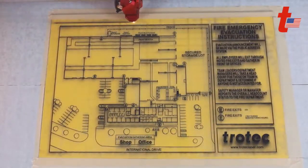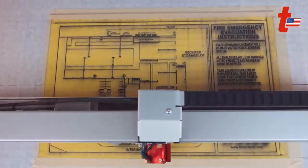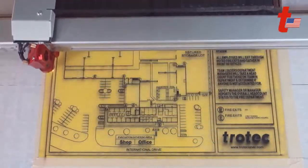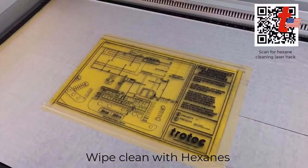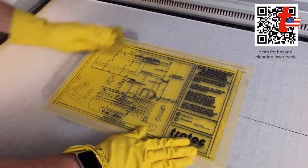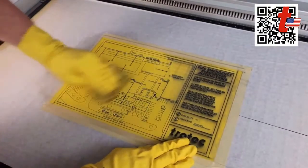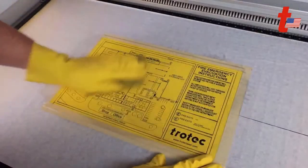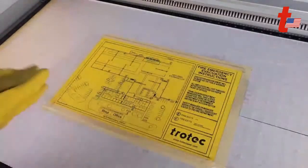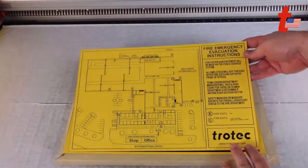So that black residue, the reason I do it in one pass in this case is because I will typically clean it up with a Hexane cleaner. Hexanes are nice because you don't need to worry about any residue. Here's a little QR code if you want to see where to get that. Hexanes work nice, a little bit on a rag. Make sure to wear gloves and just dab a little on the rag and it'll wipe right off. Most cleaners don't work this well with it, so this is why I was able to run this in one pass. If you don't have hexanes, then run it in 2 passes and you get a cleaner response.